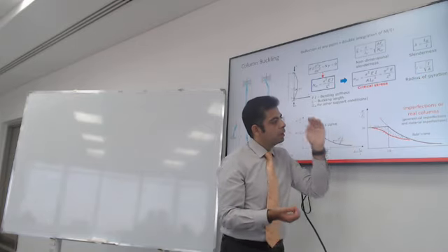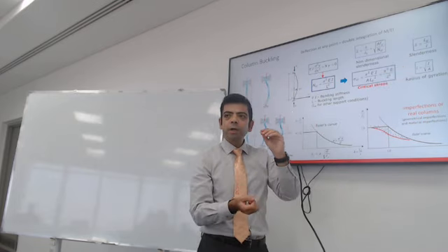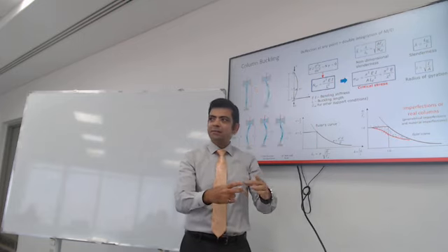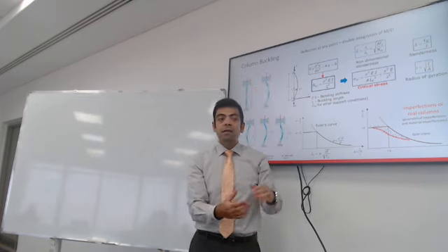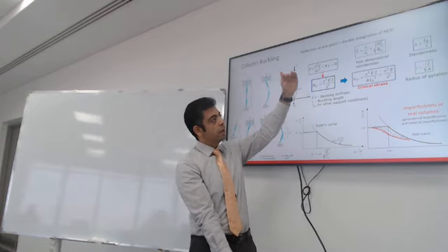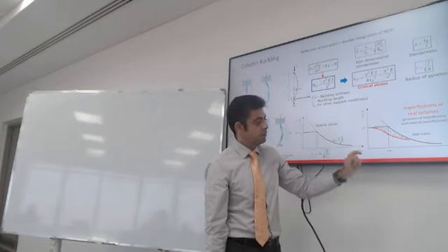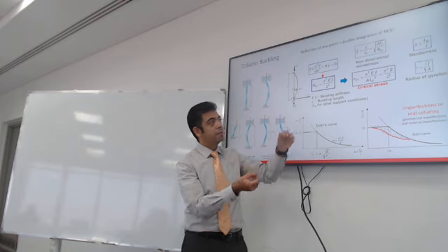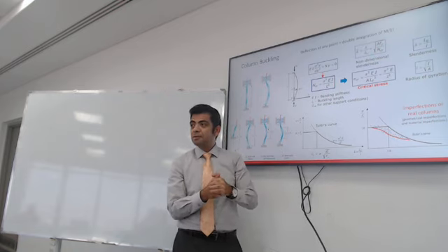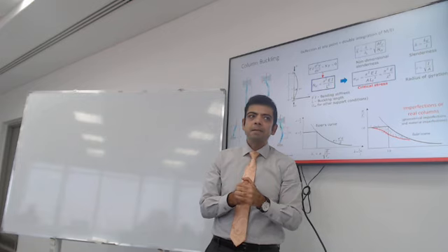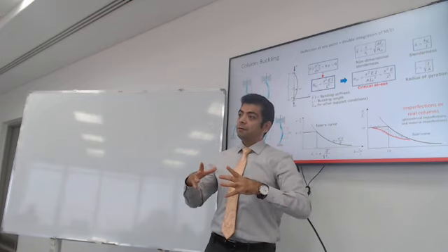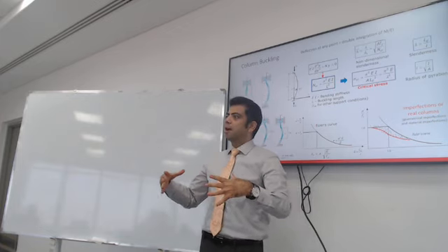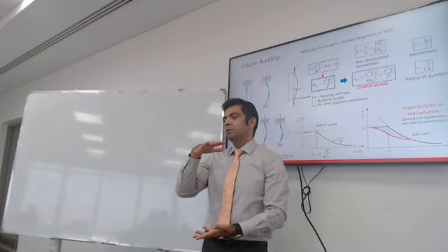All right? So lambda is the ratio between the length or the height of the column and its stiffness, how strong it is. The taller the column, the bigger lambda is. So this is a relationship between lambda, or slenderness factor. What does slenderness mean? Slenderness means is the column stiff, or is it small and slender and flimsy? So a stiff column is usually big in dimension, short in height. So that's a very stiff column.